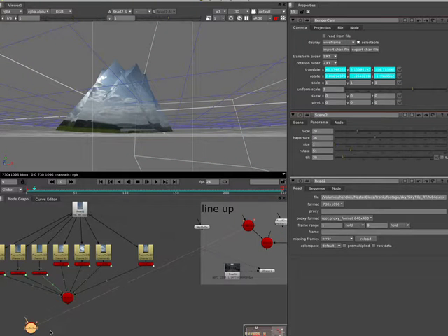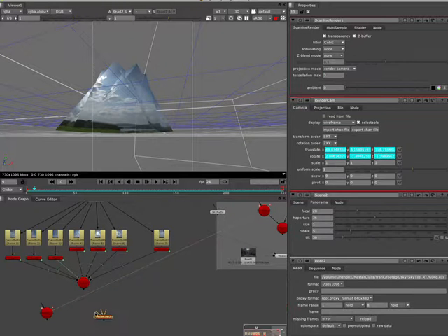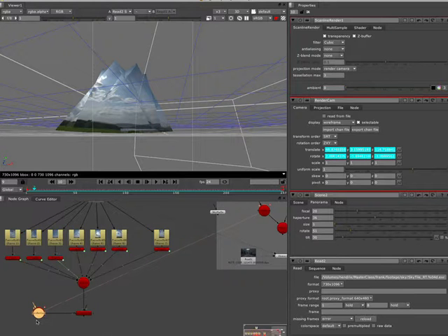And then I've got my expression links here, right? So I can see that this is like a clone link between them. And I'll just make a scanline render node. As promised, I'm using the tab thing, and connect them up, right? And if I hit Alt and E, I can hide those expression links. There's going to be a few clones and expressions in this script, and it's going to get a bit messy. So if you have them all there, it's going to look bad. I'll just hide them out. It's a bit easier, right?